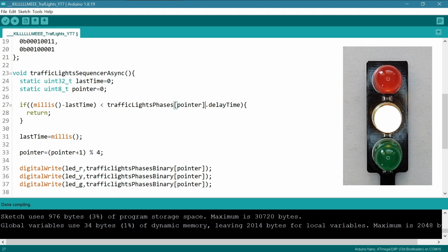And now I have to do some bit magic here because I need to get from the... Oh, let me change this here too. And now I have to do some bit magic because I have to get from this thing, this is a byte, to a bit. And Arduino in its whole wisdom gave us a function for that. It's called bitRead. Did I do that right? I did do that right.